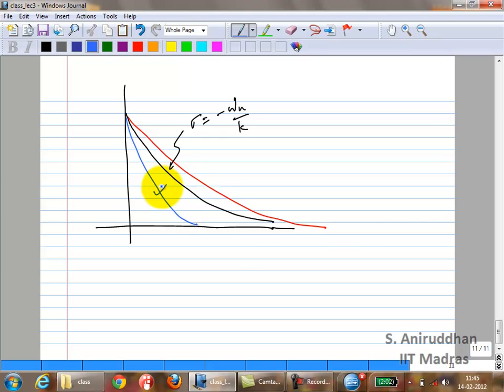Why do you think this is? Because in this case there is no overshoot. We are still not seeing the case with any overshoot. What you are seeing is that, even though your error is decreasing, you are still accelerating for a little bit longer than is necessary in a first order system. That actually helps it settle a little bit faster. It is not so intuitive, but this happens to be a property: if you add a little bit of delay, you can actually settle faster in this particular kind of system.